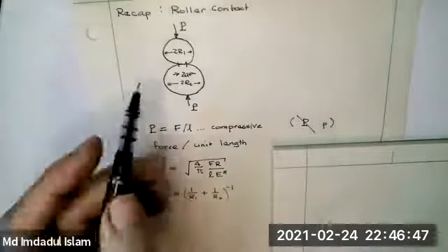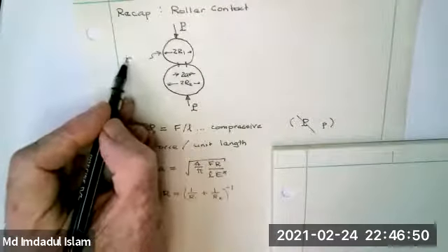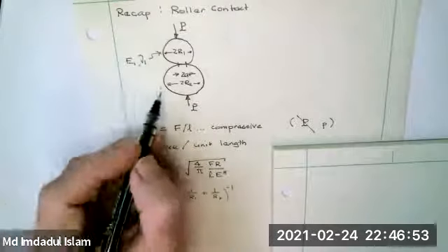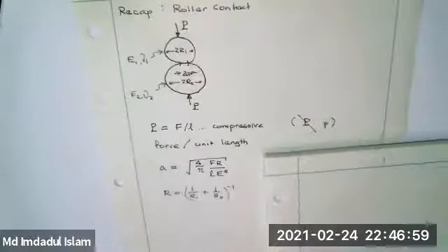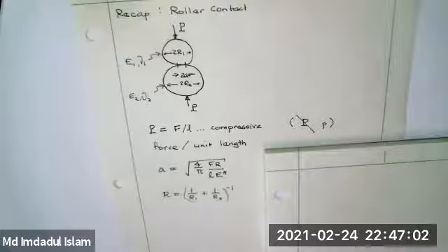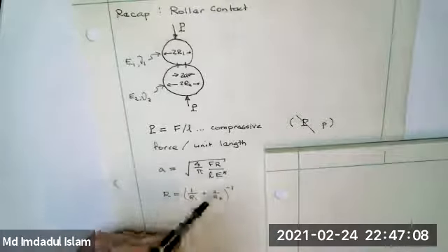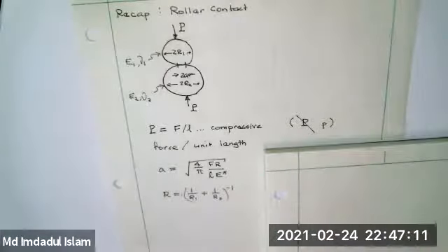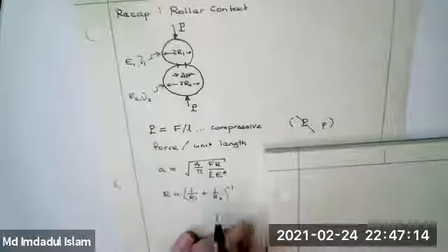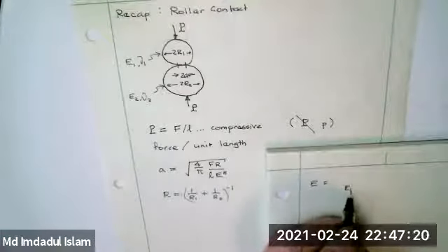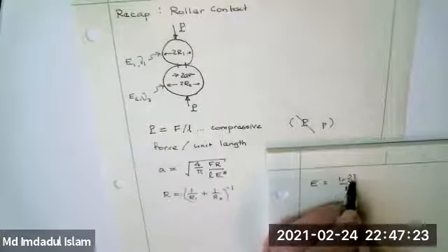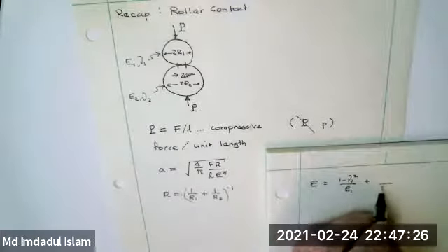E is a combined E. If this thing has a Young's modulus E1 and nu1, whereas this is E2 and nu2, you don't get straight E in here. You'd expect the stiffer it is, that's going to resist the growth of the contact region. That's why E's on the bottom. But as you push down on it, it pushes out, and that stuff pushes back. There's a Poisson's ratio effect. And so this E looks like this. That's E star, right? Yes, thank you.